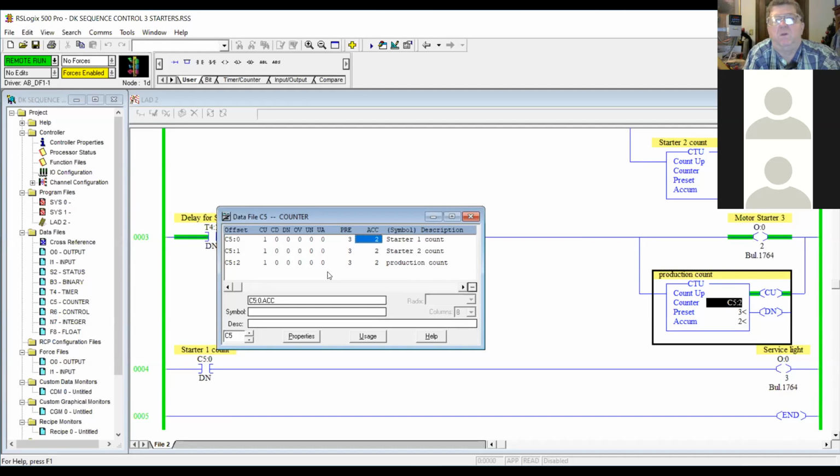We not necessarily. We really just go on visual and on wear. But it would be something neat to put in. If you got something that's super expensive that you can actually plan, and you know that by so many strokes of running, it's a lot cheaper to just rebuild and put more seals in there, than to wait till they wear down and scar a real high dollar cylinder. Some cylinders are really expensive and some are just throwaway.